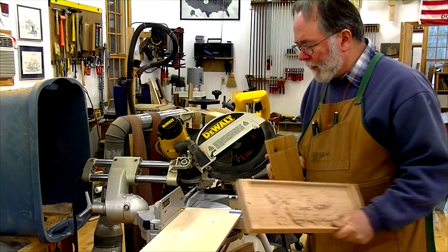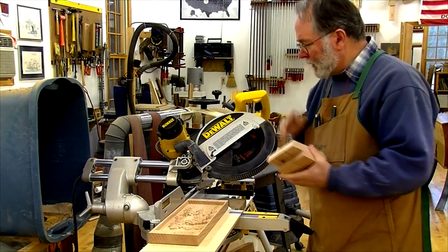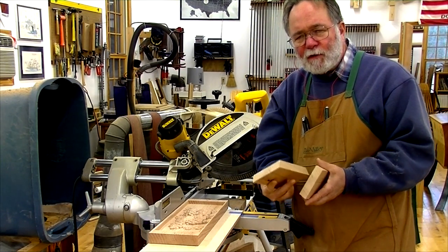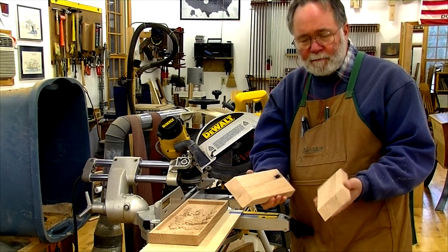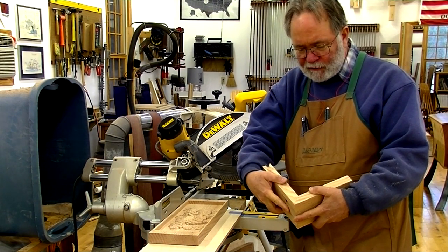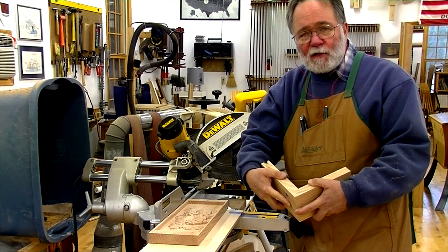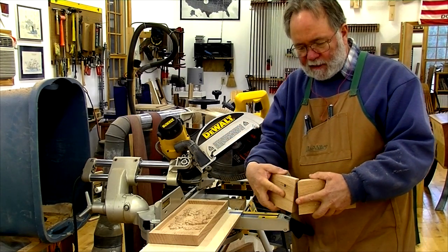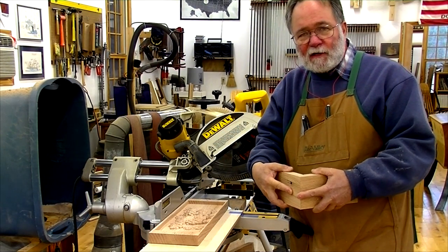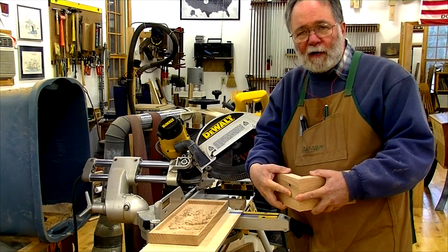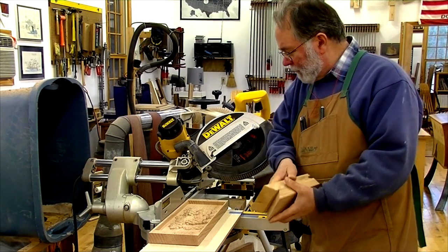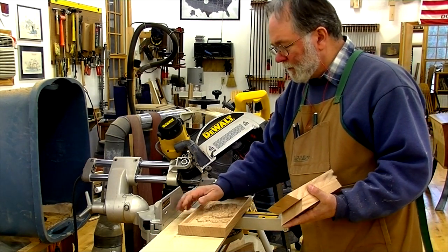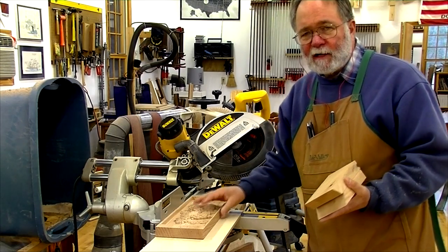Now I'm using my compound sliding miter saw, and before I do that I made a few adjustments. First I took some scrap pieces and cut some 45s on there, and then used a square to make some slight adjustments to get that just as perfect as I could. So that's a good starting point for getting those miters on there. I've made marks here, and I'm going to go ahead and use a backing board to prevent some blowout, and we'll go ahead and cut the miters.